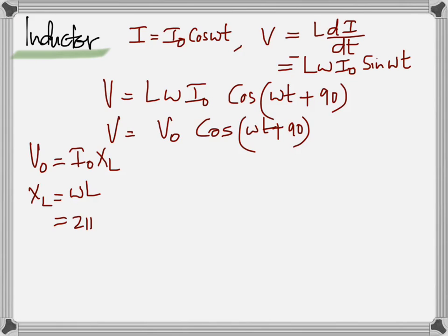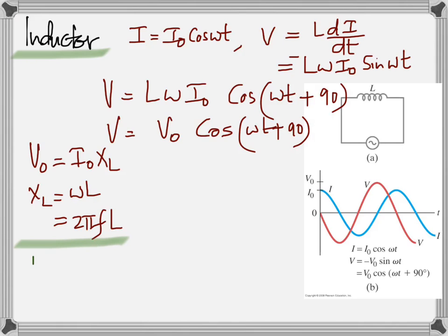So the term reactance is exactly the same as resistance. The units are the same. The unit of XL is ohm. But why do we call it reactance? Just to show you that a resistance does not depend on frequency, while a reactance does depend on frequency. I hope you understood that. Did you get that? Same unit, but reactance depends on frequency. And this is more important than I ever can tell you.